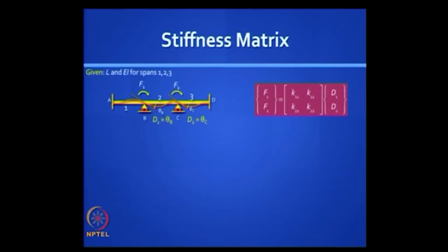You can do it. The great advantage of knowing that stiffness matrix, which is a property of that structure, is if someone were to give you the displacements, which is very unlikely, you can find what forces caused it. But the more common problem is you have some known loads F1 and F2, and you have to find D1 and D2, and from that knowledge of D1 and D2 you must draw the bending moment diagram. So that you can do if you invert this matrix.